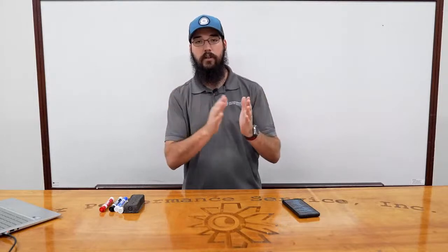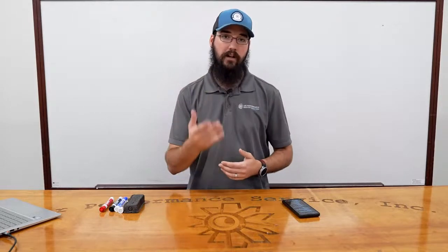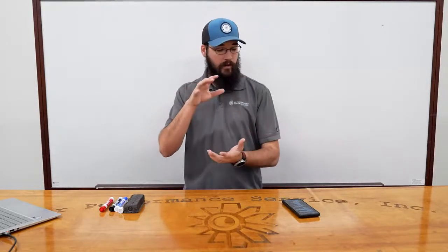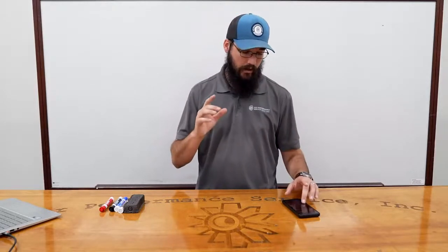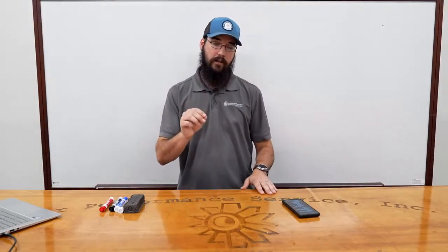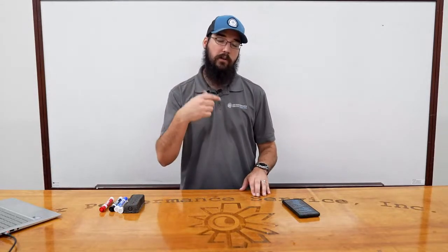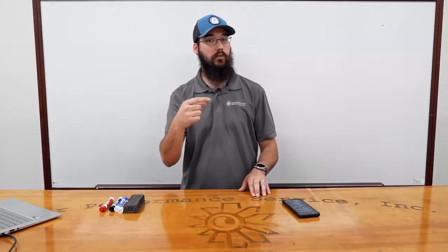And you have a thing called total static. Then you have velocity pressure, you have total pressure, and then static pressure. Now we commonly talk about the static pressure side, and actually I'm realizing I meant to get a manometer, and I didn't do that. Anyway, we talk about the static side, but static is actually only one of 3 total readings that we can use on a given system. Now, I don't want this to be overcomplicated. So we're going to hone in on the static piece, but I want you to know that the others exist, and the others will become more important in the later classes.